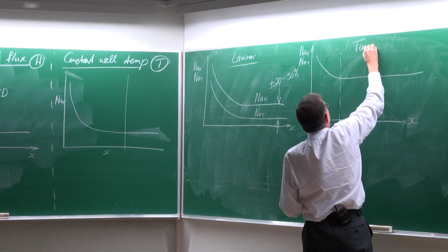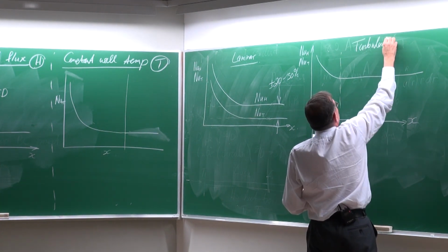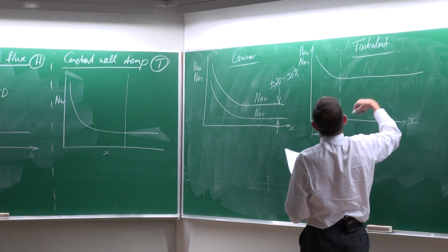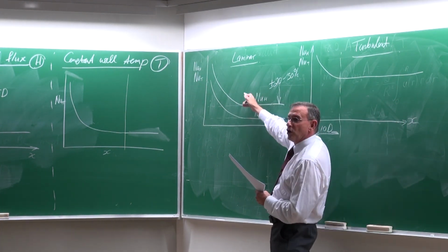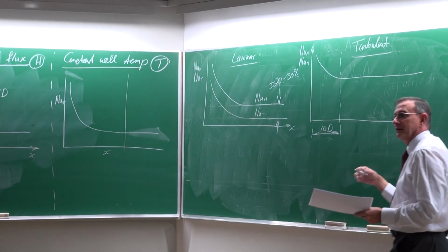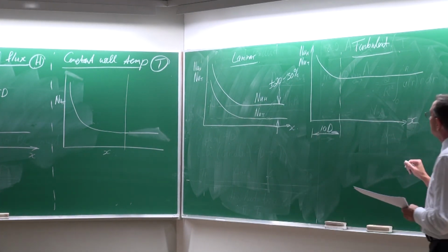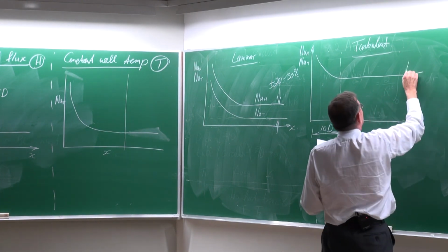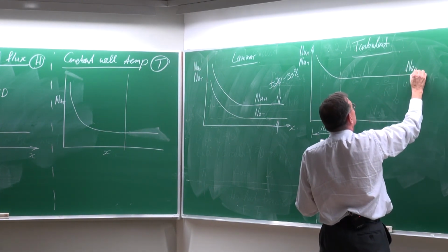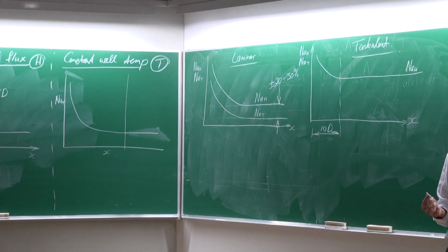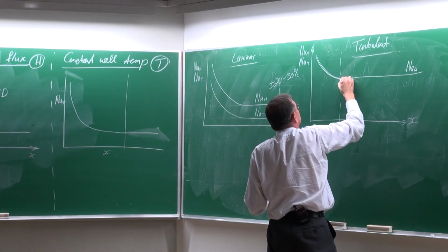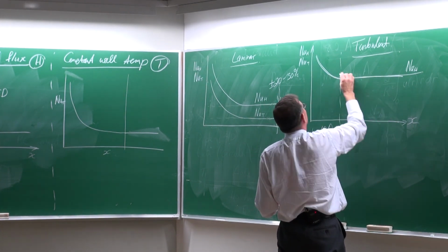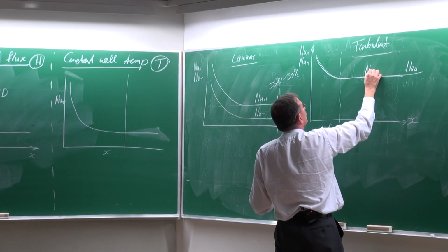So this is turbulent. And take note, I'm drawing these values to a larger value in terms of the scale next to it. So that is going to be for Nusselt number H. And who would like to guess where the Nusselt number T line is going to be? Well, they sort of do something like that.